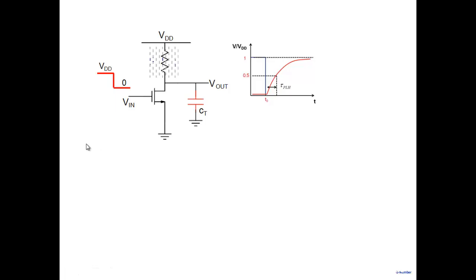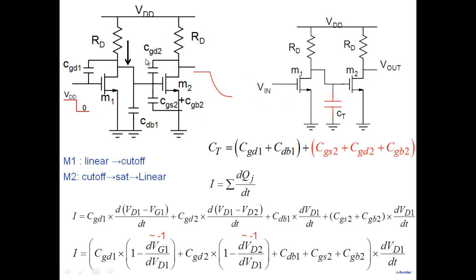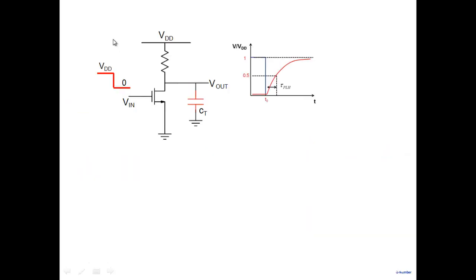All right. So now note that we are talking about a resistor, right? We discussed the inverter in the form of a resistor here. But similar things will hold if I replace the resistor by some other element. And we have been saying that the role of the resistor is to pull this particular node to VDD. The role of the NMOS is to pull it to ground.